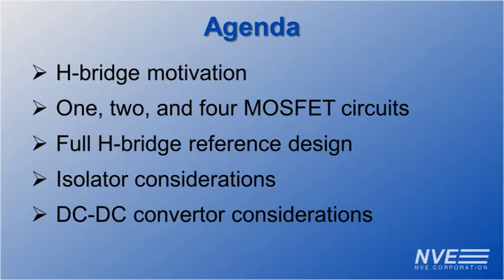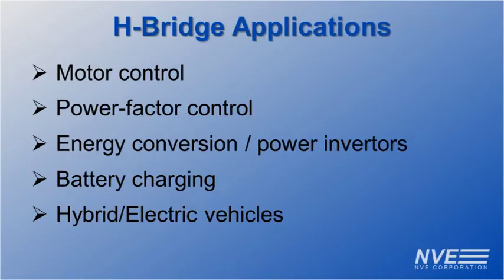Here's our agenda. We'll cover the motivation for H-bridges, show an isolated full H-bridge reference design, and go into some details on key components. H-bridges are used to control power to a load in applications such as motor control, power factor control, energy conversion, power inverters, battery charging, and hybrid electric vehicles.